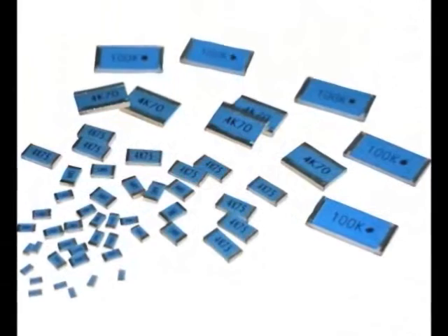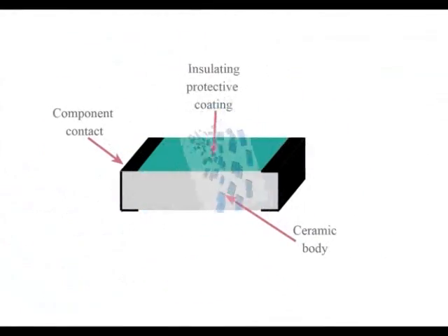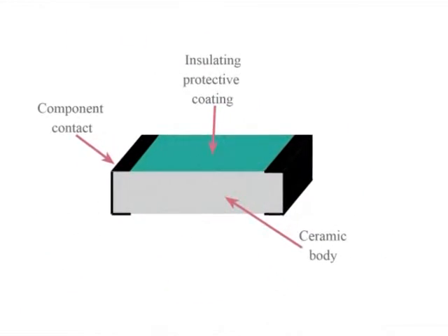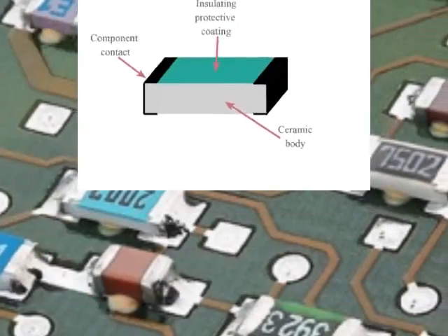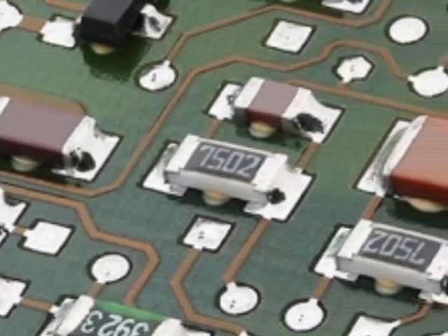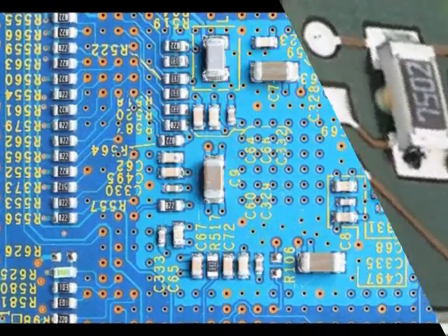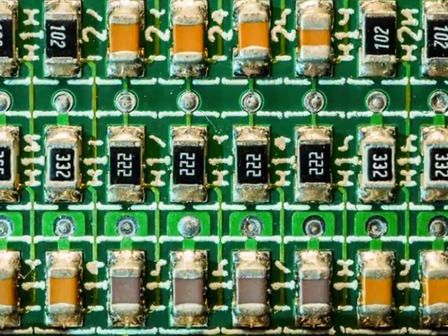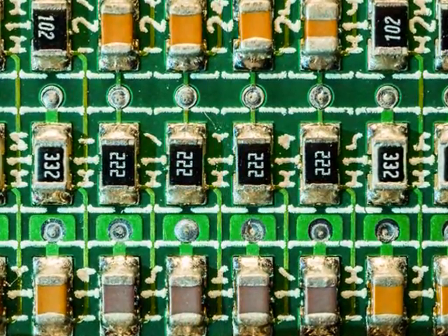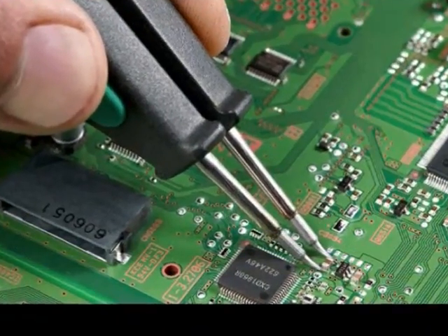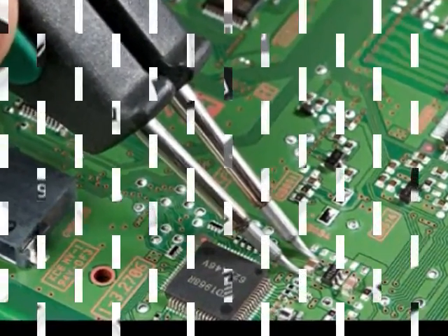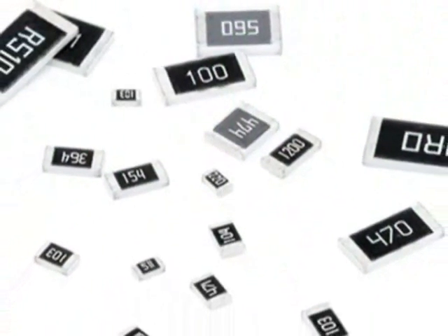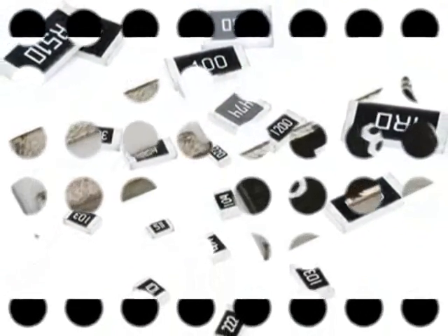These resistors are rectangular in shape and are also called chip resistors. The resistors are made of metal and can be printed on the board. The design of this resistor can be done using ceramic or aluminum materials. The resistance can be calculated based on the thickness, length and materials used. These resistors are enclosed using a protective cover with successive layers. Protective coating layers prevent mechanical damage but do not stop the penetration of moisture and other contaminants.